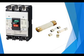Each of these conditions have devices that can help protect our circuit against it. In the case of an overcurrent or a short circuit, we would use either a breaker or a fuse. And the idea behind this is that we'd have that rapid current buildup that we have with a short circuit, which would take out the filament inside the fuse, or it would exceed the limitations of the breaker, and it would automatically disconnect the circuit. To better understand these devices, we're going to take a look at their construction.